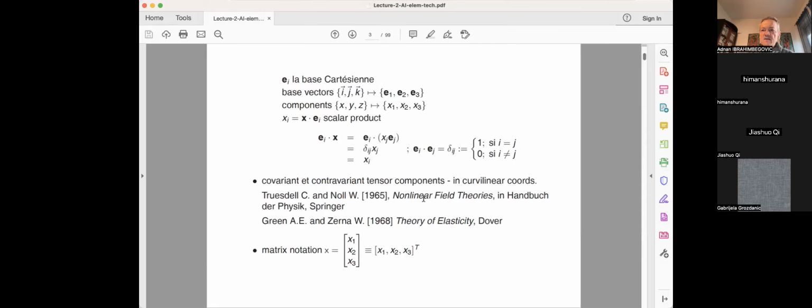So to make things simple, because it's possible in our case, we place the development that we study in a 3D Cartesian coordinate system, keep these unit vectors fixed, the derivatives in time are 0, and then taking out a particular component is simply done by the scalar product of this vector, for example, talking of position vector x, with respect to a coordinate basis Ei, and then you simply do the scalar product of these two, you get the component xi. This is easy to show, basically, because you have orthogonality between these base vectors E1, E2, and E3.